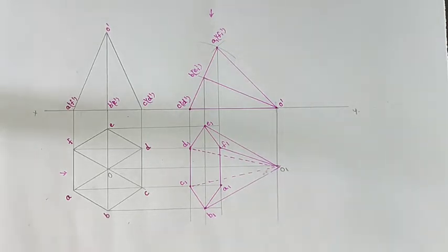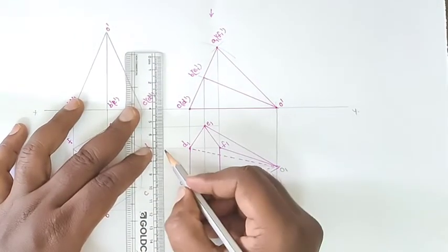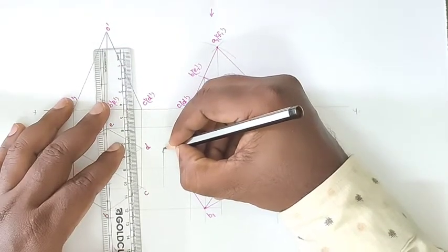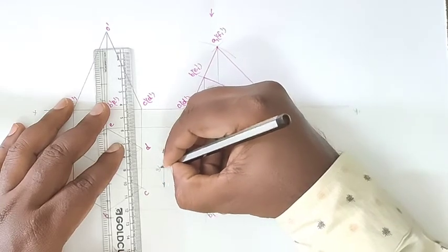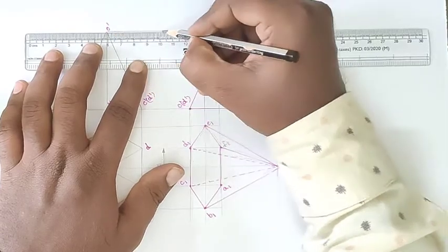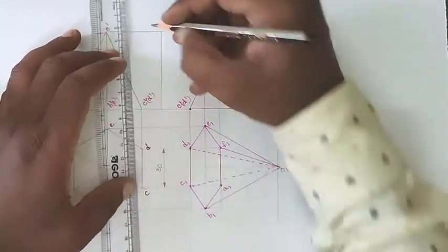After drawing the second front view, draw the vertical projection lines from the second front view and draw the horizontal projection lines from the first top view, locating the corresponding intersecting points, and draw the final top view of our diagram. So this is 30. This dimension is given. So this dimension is 60.